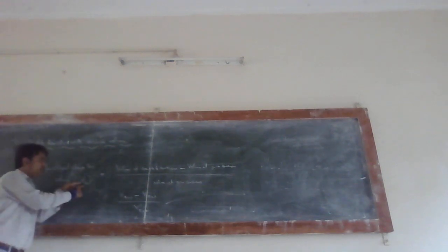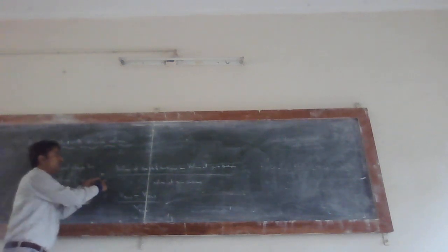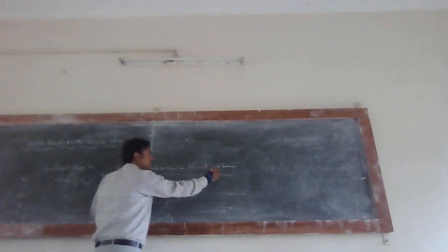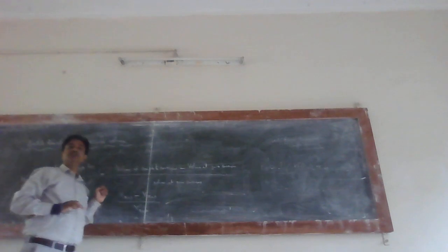If I start a reaction with, let us say, volume V0, the volume will subsequently change to V after the reaction. So you cannot use V all the time. You may start with V0, but it will definitely change to V. Now, the fractional change in the volume can be represented with epsilon A, which is equal to volume at complete conversion minus volume at zero conversion, divided by volume at zero conversion.